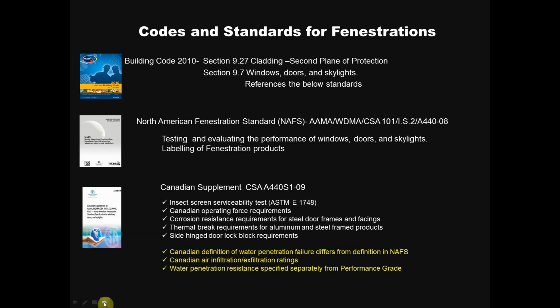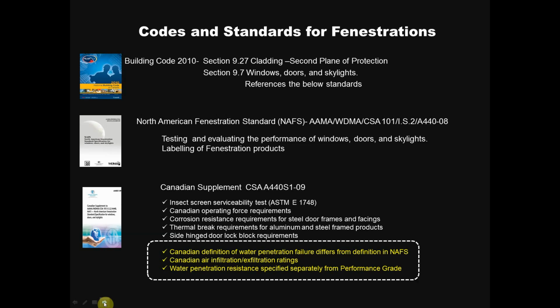The biggest thing with that supplement, which makes it a little more stringent, is that the definition of water penetration differs from the definition in NAFS. There's also the air infiltration and exfiltration rating, and the key one here is that water penetration resistance is rated separately from the performance grade. So that Canadian supplement adds a little more strength to it.